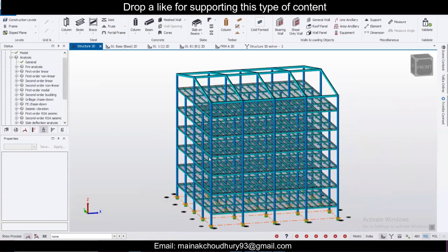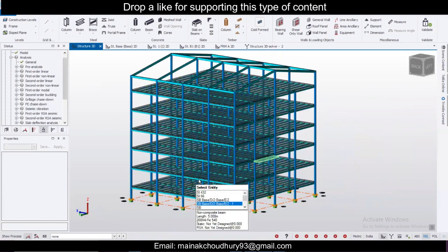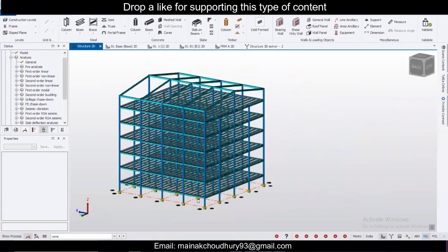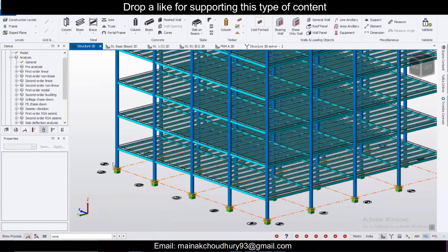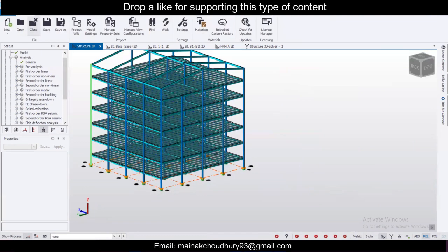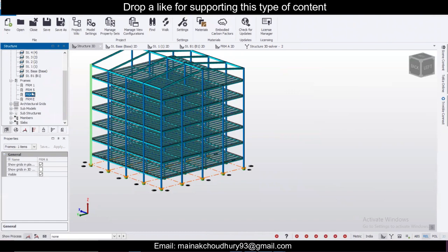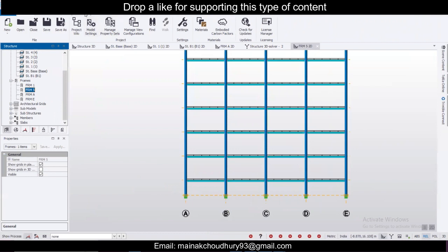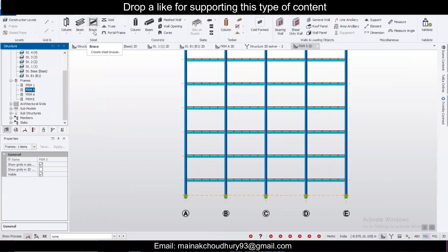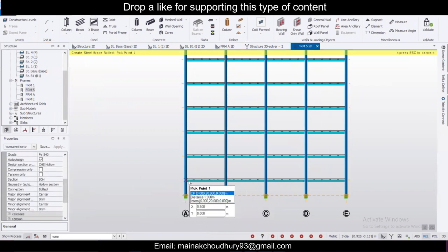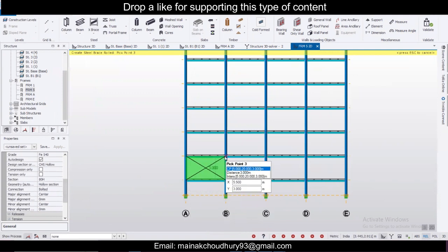And now we can place some bracings. So for that, I'll go to these two portions and provide the bracings. This is grid number 5 and grid number 1. So we'll go to home and just click on these frames. Frame number 5. We'll select this and we'll go to model, bracing and express. Okay, I can select again the column grid and the section also. So like this you can provide.